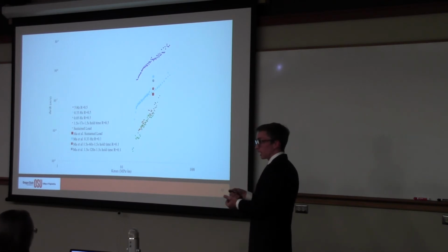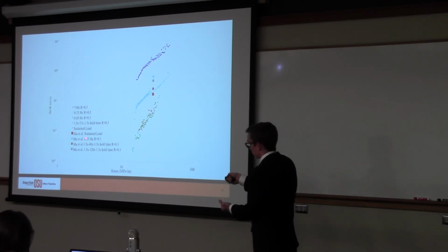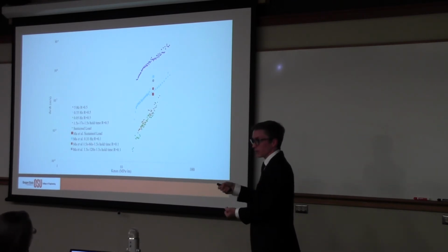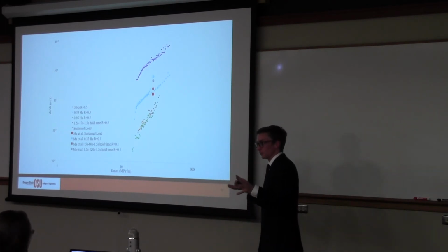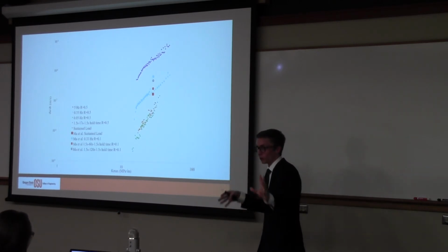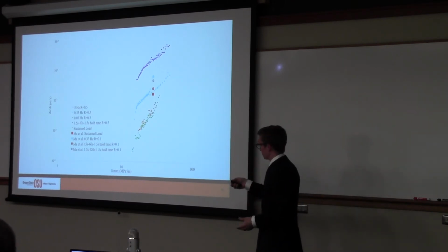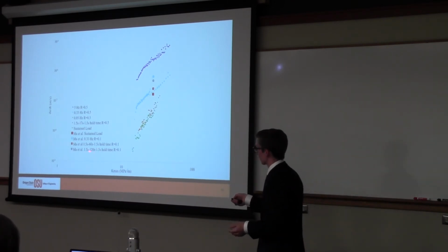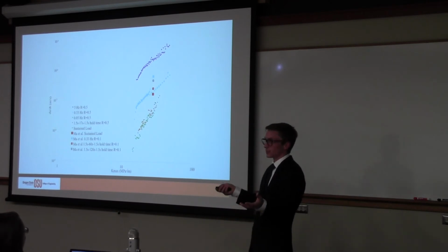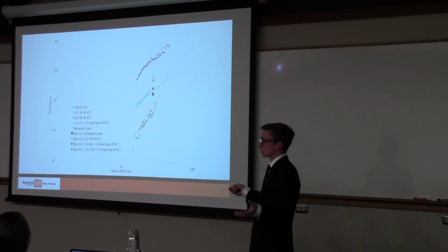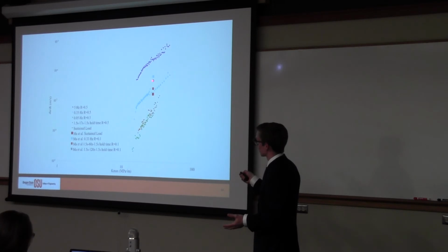It means for a long hold time, when you test at 0.33 hertz and then you test that 60-second hold time, you're going to get extensive creep in the uncracked ligament. It's going to be defined by a creep zone, and you're going to get those low energy dislocation substructures that we talked about earlier forming, providing this hidden damaging mechanism. When you apply the 120-second waveform, you're acting on material that's already ready to break, right? So of course you're going to get this little gray box up here.